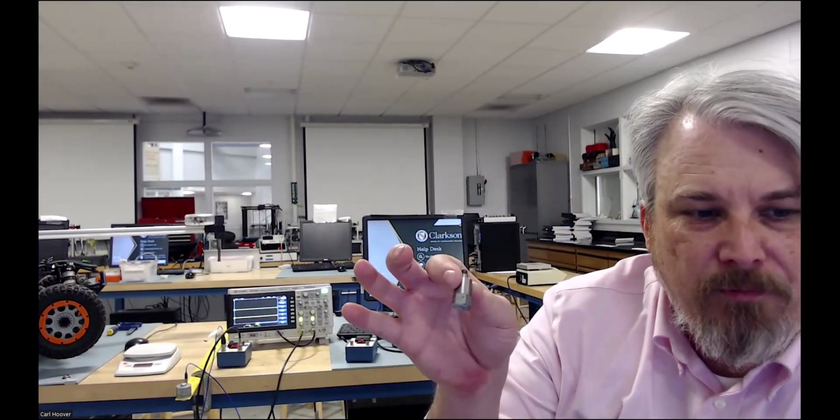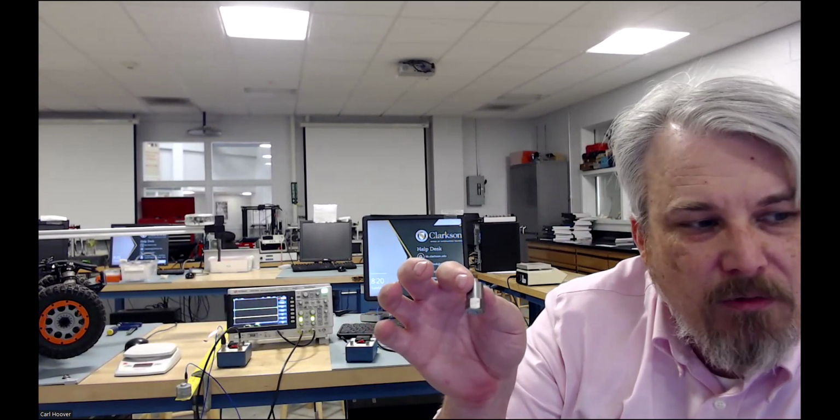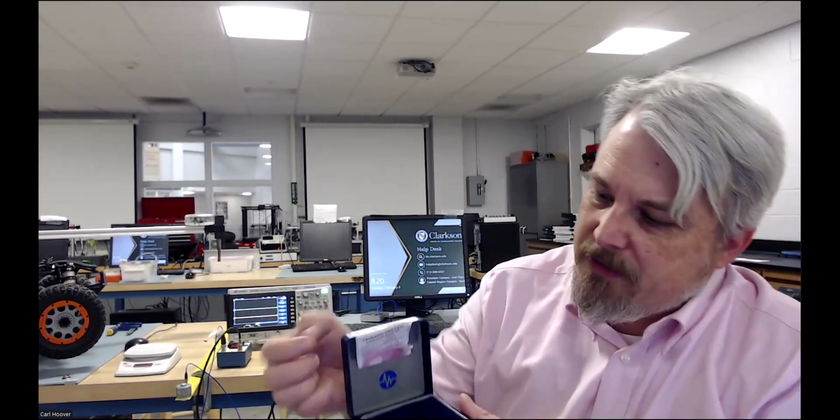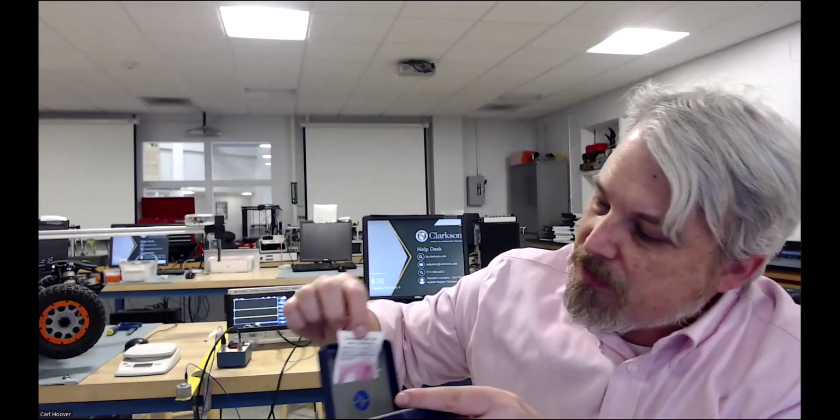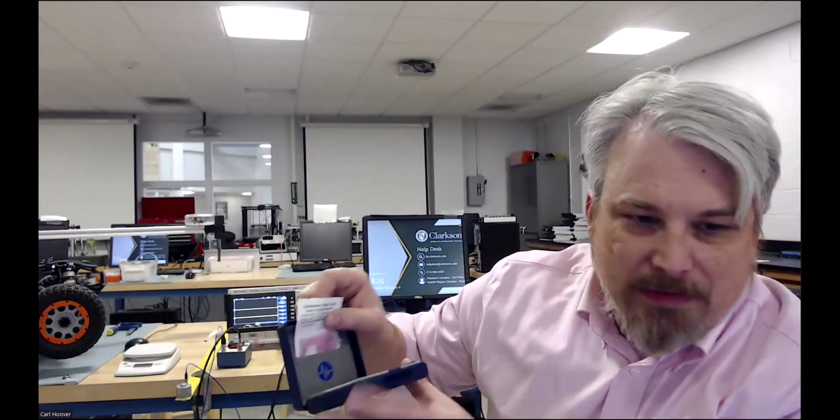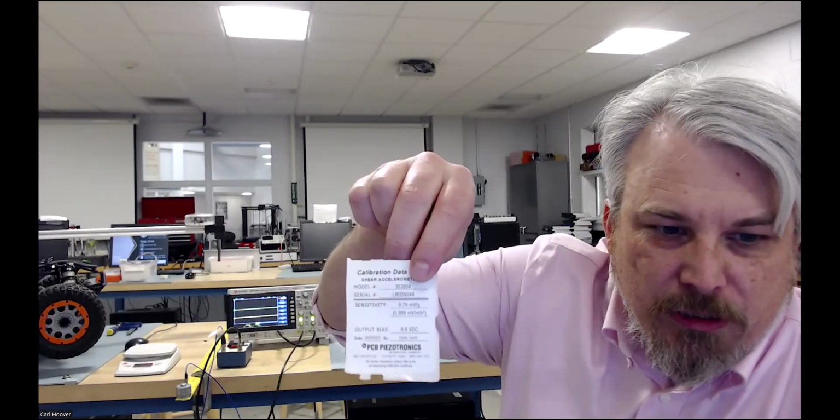Here we have a small accelerometer. This is a piezoelectric accelerometer. There's actually a quartz in there. It sits on a little mass that goes up and down on the quartz, and it generates a charge as it's shaken. It has a pretty high G range, and the accelerometer comes in a little box like this and has some calibration specifications. Here, for example, 9.79 millivolts per G is a sensitivity, along with some other specs. So this accelerometer has a 10-32 thread under here.